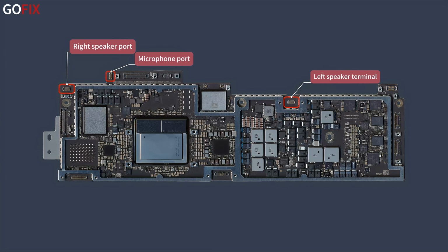Let's focus on the storage core part of the motherboard. First, let's look at the SSD chips. UN000 and UN100 are the NAND flash chips. As you can see, this 256GB base model only has the UN000 chip installed. If it's a 512GB or higher capacity model, 2 chips will be installed.